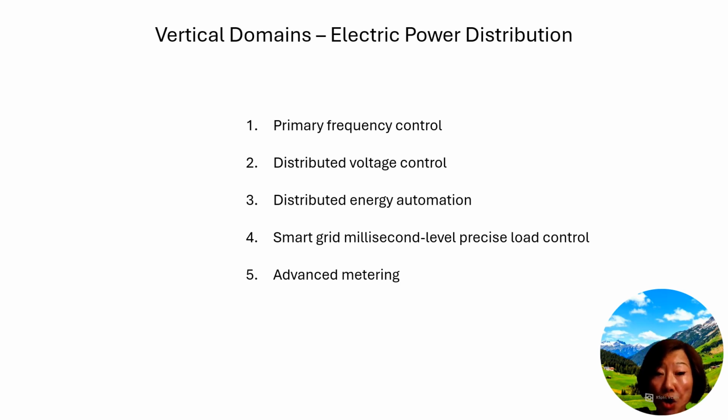For distributed voltage control and energy automation, 5G supports wide area IoT technologies like narrowband IoT and LTE-M, which stands for machine, which provide extensive coverage and good building penetration. The system also employs advanced multicast broadcast techniques to efficiently disseminate grid status information to many devices simultaneously. Supporting protocols like IEC 61850 involves careful mapping of protocol messages to appropriate 5G quality of service classes.